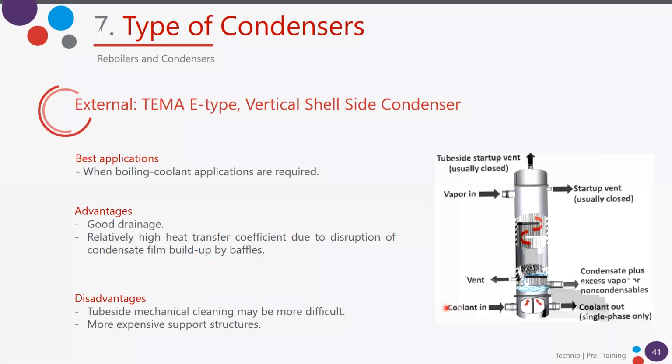When we start entering the cooling water, we will have this opened, but then it will remain closed. It's just to dispense any vapor inside the tubes at the startup, because usually maybe they were under preservation or whatever. Exactly. Okay.